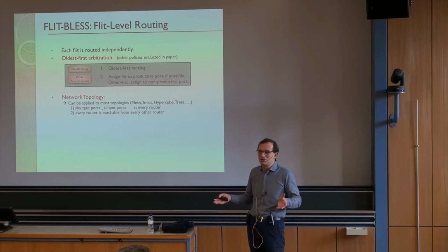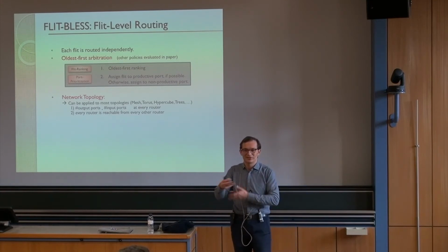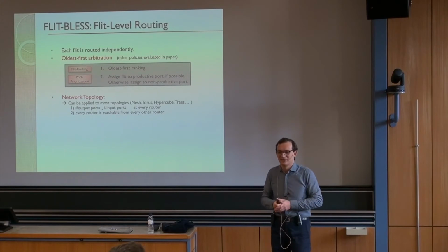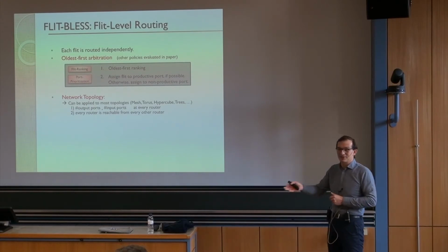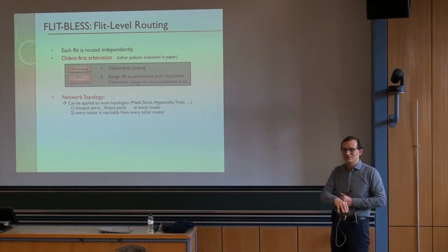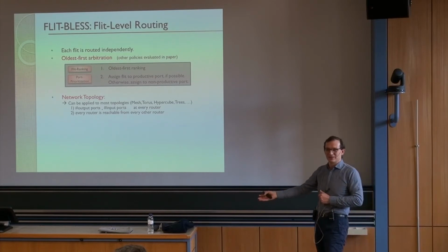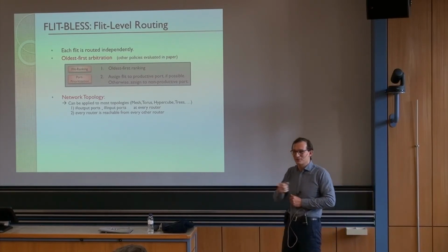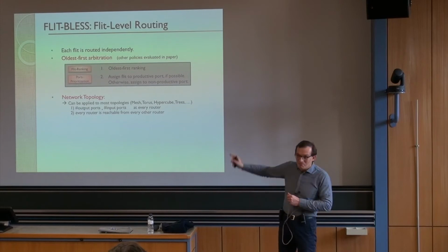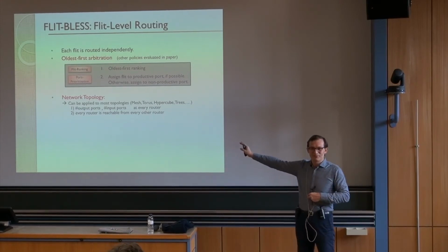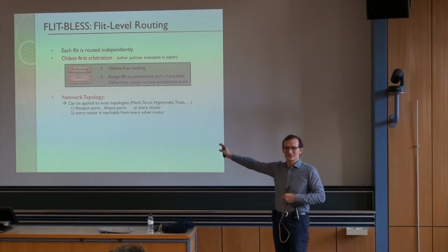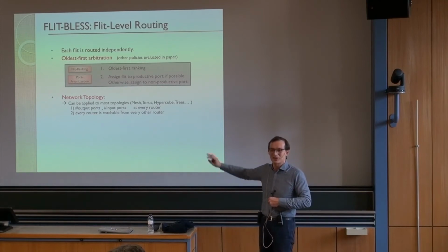In general, you don't really care about how you deliver the data, right? Actually, we break that even in the memory systems. We do a critical word first fetch from the memory system. So we try to fetch the critical word first. That may affect the delivery, but I think you can add priorities on top of this to say, this is a critical word, so try to prioritize it.